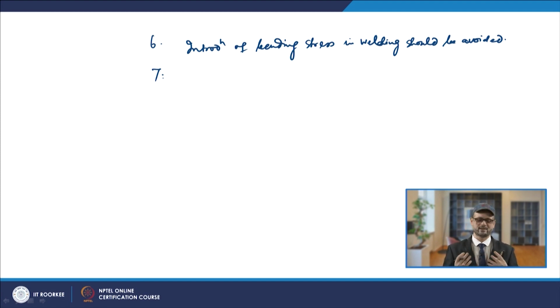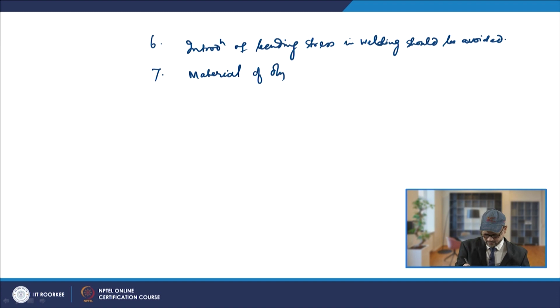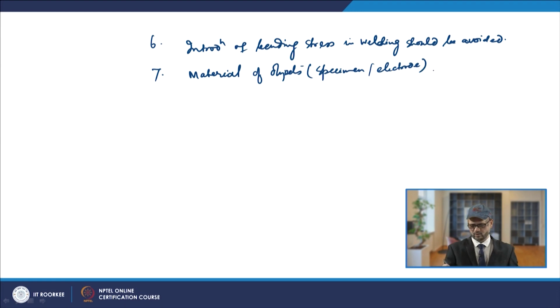The material of the specimen and the electrode should be selected carefully, because if the properties of the electrode material are vastly different from those of the material to be welded, there is a likelihood of the development of stresses.